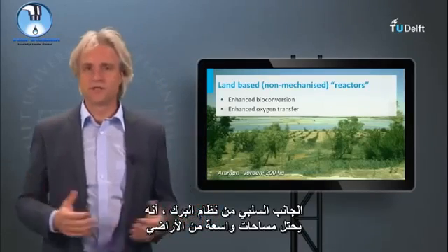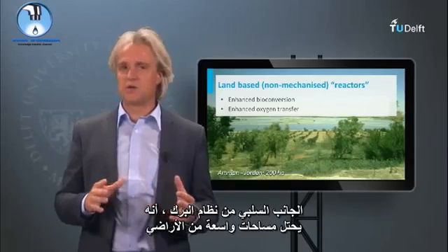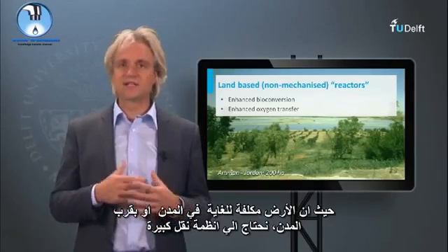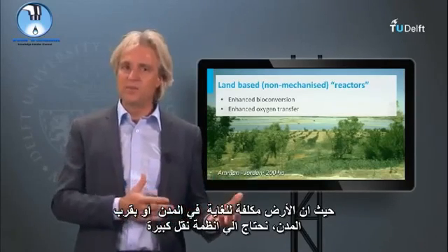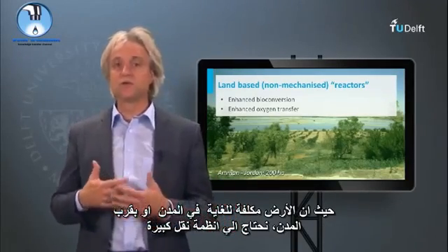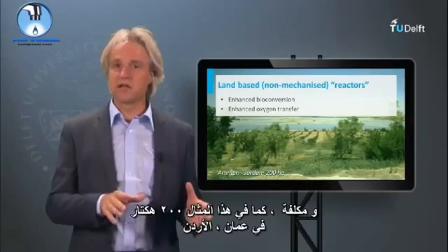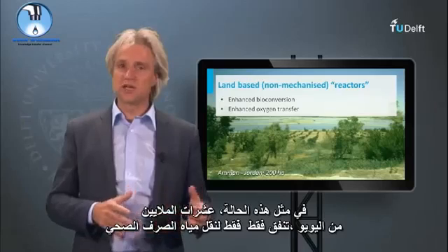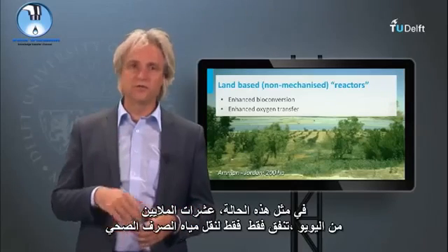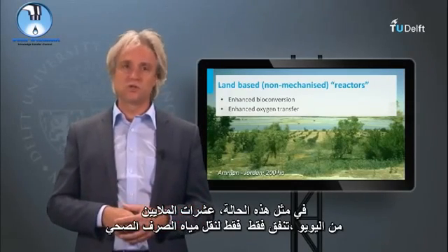The downside of a pond system is that it occupies large areas of land. Since land is extremely expensive in or nearby cities, large and expensive conveyance systems are required, like in this 200-hectare example in Amman, in Jordan. In such a case, several tens of millions of euros are spent only for sewage transport.